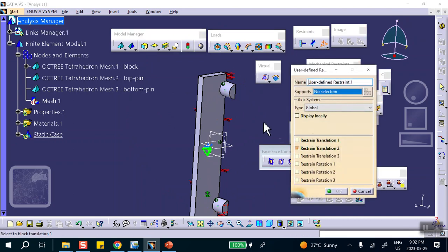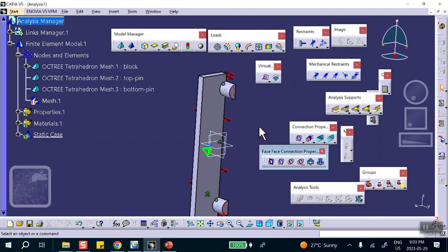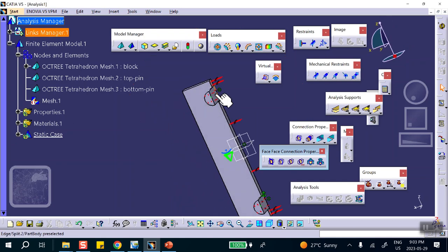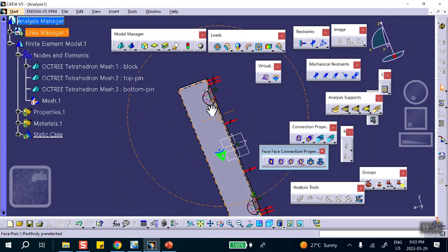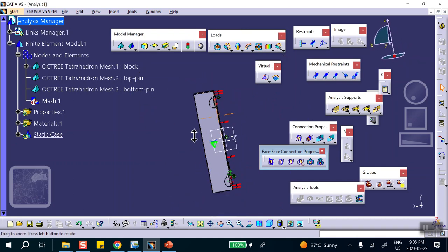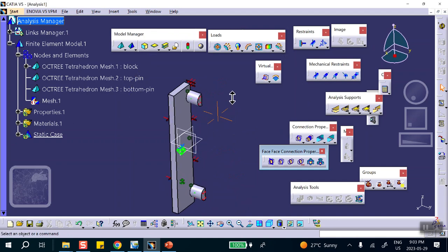Now, I'm going to say, I want to pull this thing up, remember? So we're going to say this piece in the vertical direction, which is Z, 0. Now, remember this pin was going in and out? It cannot go in and out. However, it can still spin. I will leave it like this to show you that we may have to come back. Actually, it can't spin because of this. So that's okay. It will not come in and out, and it will not spin. So this should be good. Okay, very good.